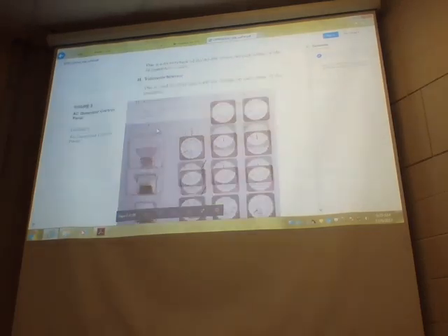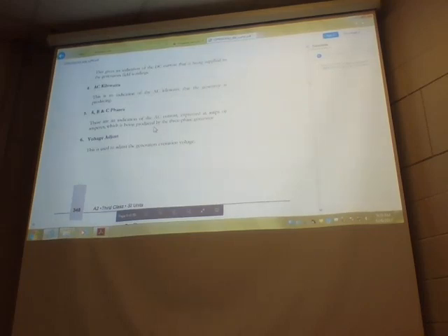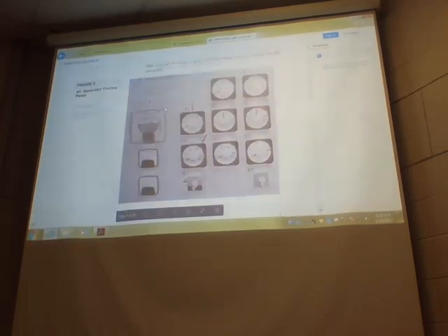Number 5, A, B, and C phases are indication of the AC current expressed in amps or amperes, which is being produced by the 3-phase generator. So you can look at these 3 ammeters, 1 for each phase. There'll be an ammeter with a current transformer with a conductor passing through it, seeing that magnetic field, and showing you on this ammeter how many amps are being used on each of the phases.